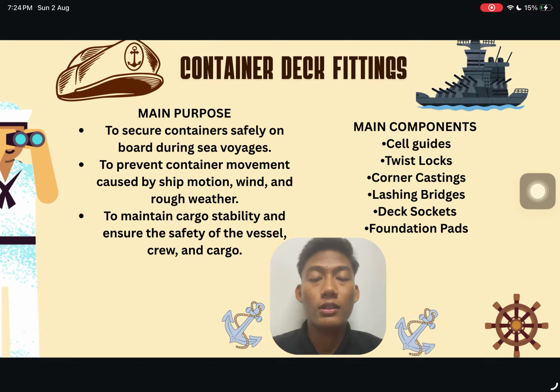Today I will explain about container deck fittings. So, what is container deck fittings? Before I explain each component, container deck fittings are basically a securing system used on container ships to keep containers in a safe position during the voyage. So when the ship experiences movement such as rolling and pitching, these fittings help to prevent the containers from shifting and maintain the stability of the cargo.